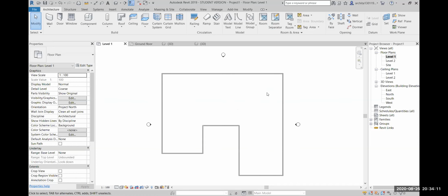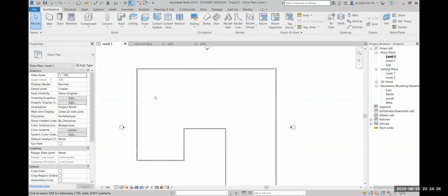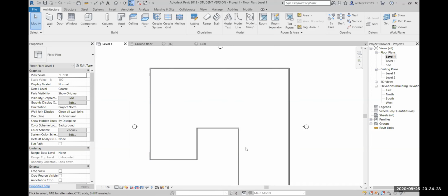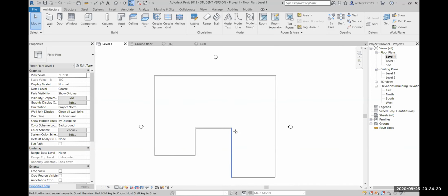Done, guys. Could you all create the wall using the floor plate? Basically, I wanted all of you to use the pick line command. The pick line command is going to be very helpful. Now, another thing which you have to see over here is how to add false ceiling. So we can even add false ceiling.